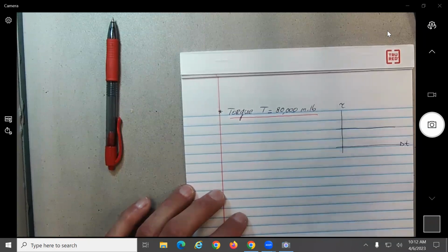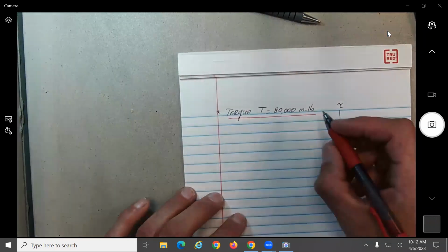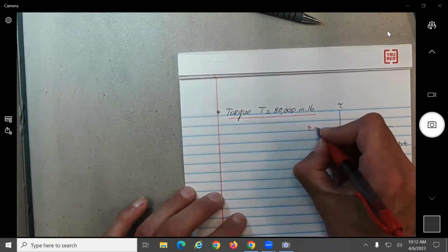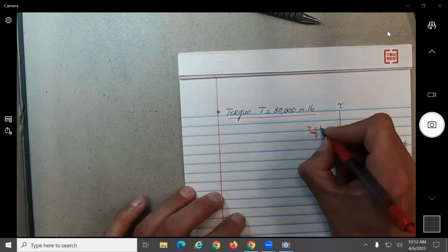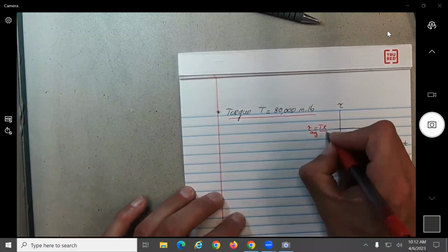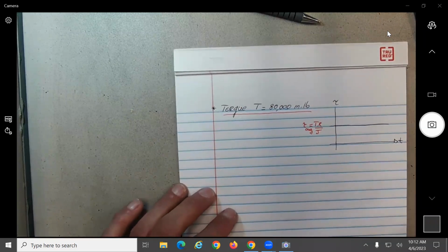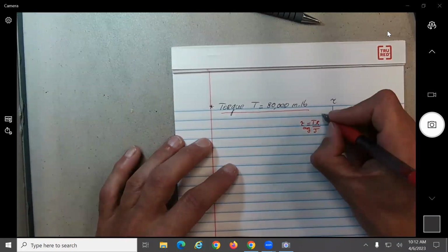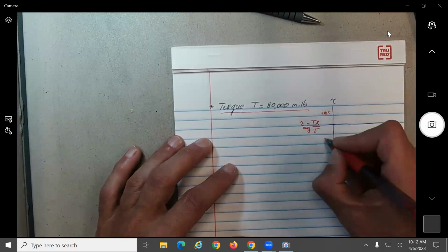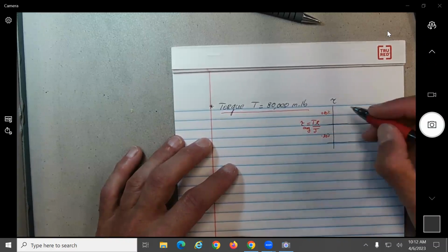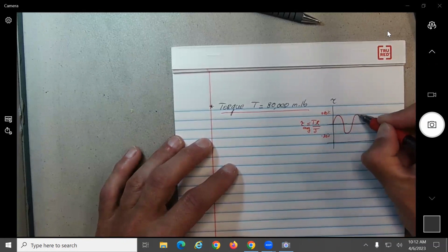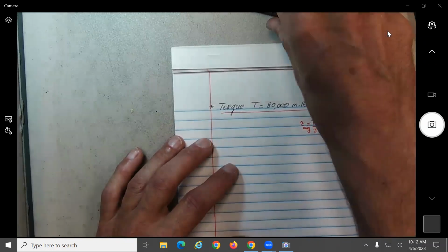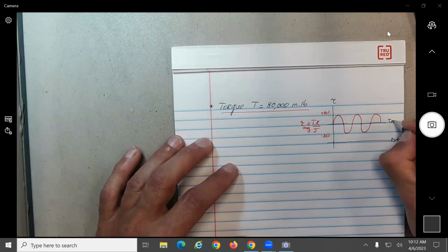This will be the shear, what you just said, that it will be fluctuating between whatever stress is due to the 80,000. So let's say it will be TR over J, the constant value, and then let's say here we have plus 20%, minus 20%. So it will be something like this. So this will be the tau average, again from the figure.